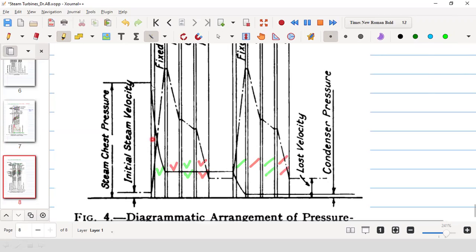So what is happening? You see, the pressure is reduced. This is the pressure reduction. Pressure is reduced once and the velocity increased. After the velocity increase, that velocity is utilized in two stages. And in the guide plates, there is frictional loss. So after the velocity reduction, it goes there. Again, there is a pressure reduction, therefore there will be some velocity increase. And that kinetic energy will now be split in two stages, 1 and 2.